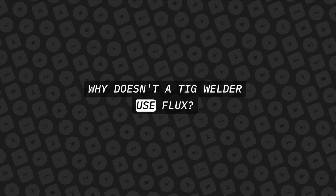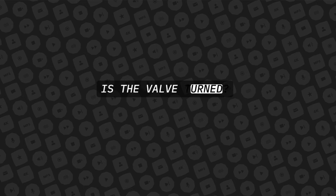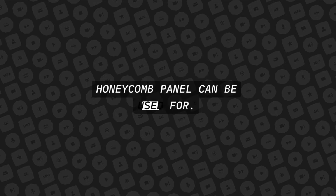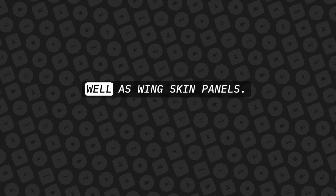Why doesn't a TIG welder use flux? It has helium shielding gas. When opening an acetylene container, how many turns is the valve turned? 1.5 times. Name an aircraft structure that a honeycomb panel can be used for. They have a variety of uses on aircraft, such as floor panel, bulkheads, and control surfaces, as well as wing skin panels.